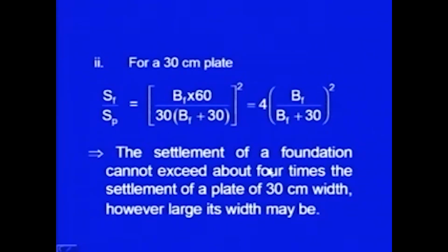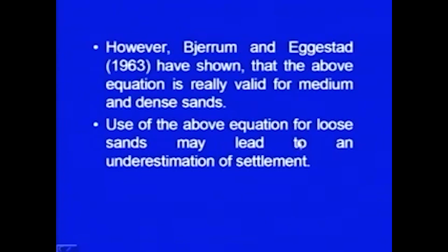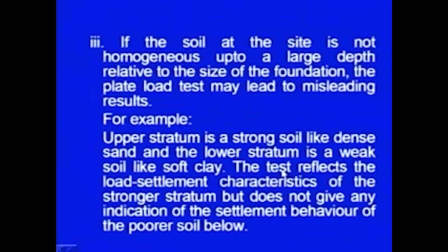So, this is what this expression gives, but it has been observed that the above equation is really valid for medium and dense sand. The use of the above equation for loose sands may lead to an underestimation of settlements. So, the important point is you have to be careful when you use this equation. For loose sands, you are likely to get low values of the settlements.